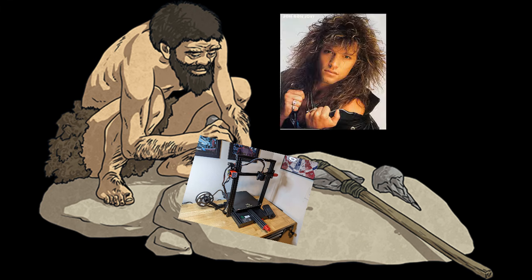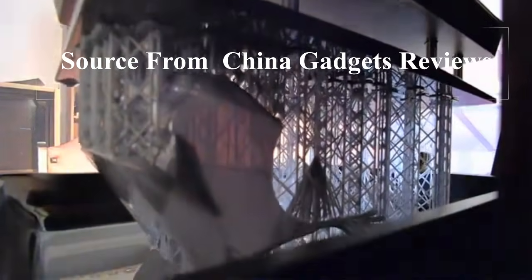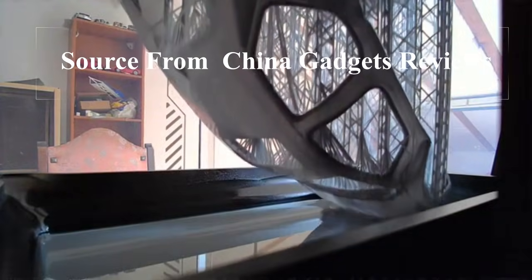What is additive manufacturing? Traditionally, in the 1980s, additive manufacture was done via photohardening thermoset polymer and used a setup we refer to as SLA. SLA printers use a laser and an array of mirrors to draw on the photohardening resin, which sets in place to form our layer. The layers are moved at one layer thickness and the next layer is drawn.